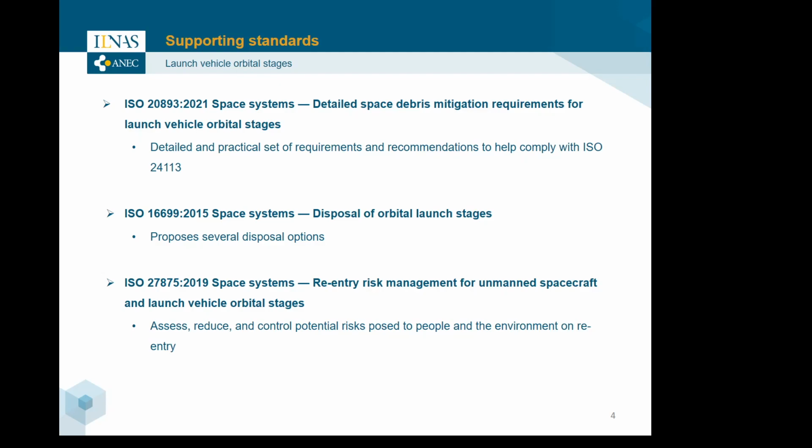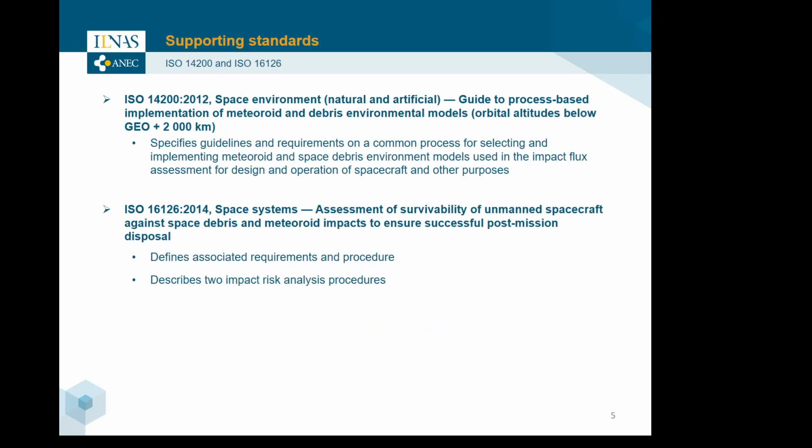ISO 27875, Re-entry Risk Management for Unmanned Spacecraft and Launch Vehicle Orbital Stages, helps to assess, reduce, and control potential risks posed to people and the environment on re-entry. We can note that it has been amended in 2020 with a modification of the formula used to obtain EC, the expected number of casualties. Moving on with ISO 14200, which specifies guidelines and requirements on a common process for selecting and implementing meteoroid and space debris environment models. It is valid for altitudes below GEO plus 2000 kilometers.